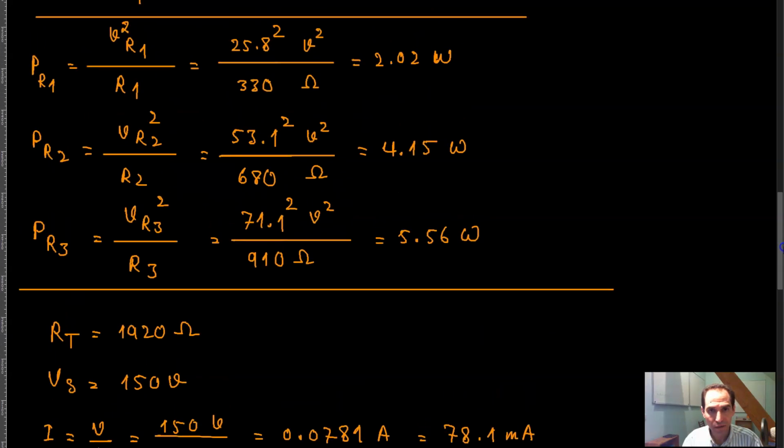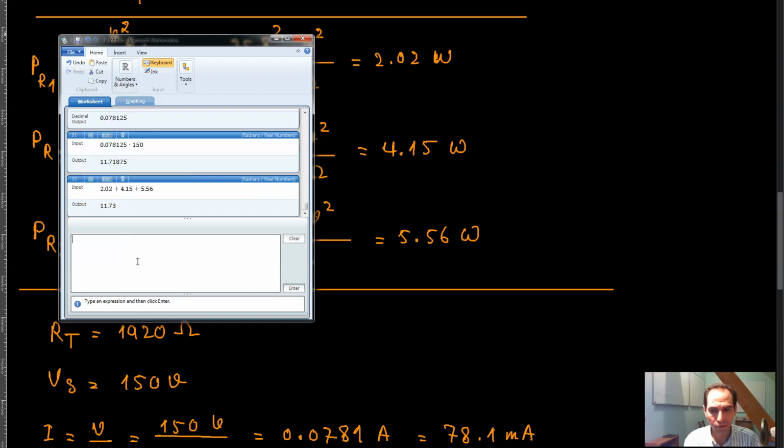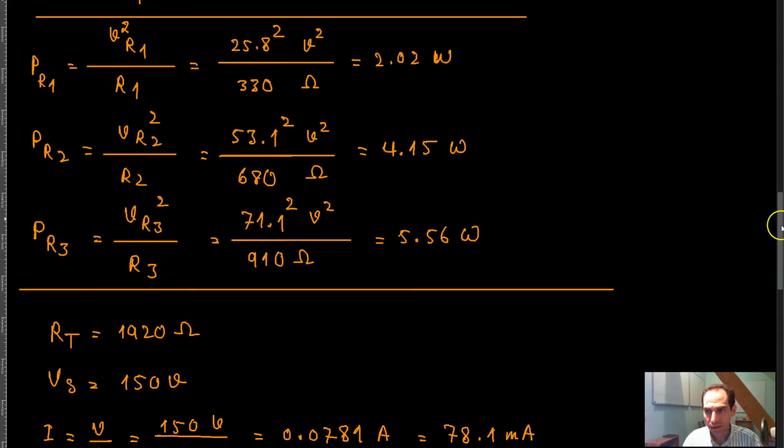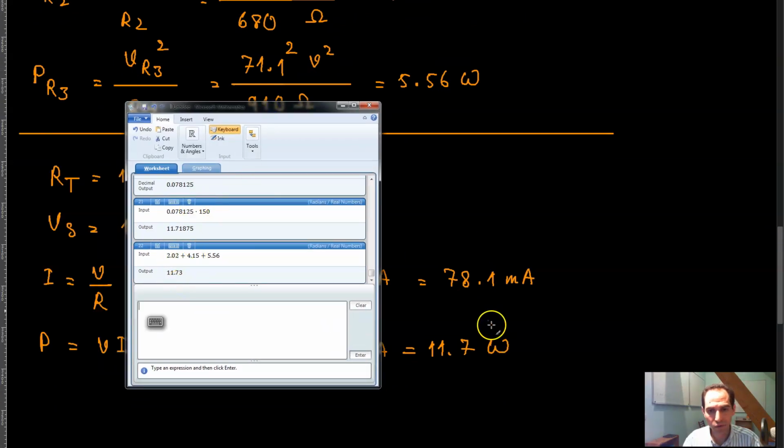Now, if I add all of these power dissipations together, you can see that I will have 2.02 plus 4.15 plus 5.56, that's 11.73 watts, and that is exactly equal to what we got over here.